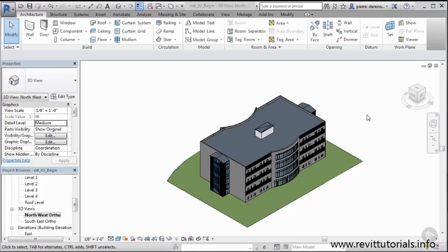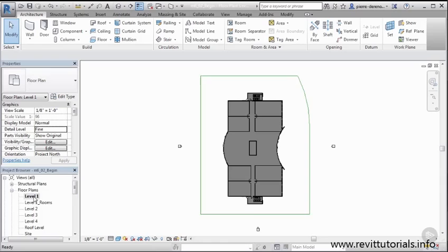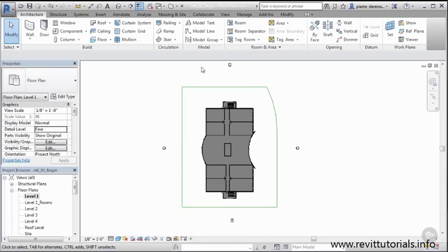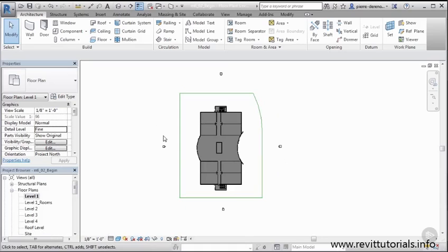So when I'm working with a camera, I can either set that up in a 3D view, plan view, site view. I'm going to do it on level 1. So let's go ahead and jump to floor plan level 1 really quick. Now, I could have done this in a site view, but I like this view here because it's going with more my project north, and I'll be able to place my camera a little easier. Had I gone with the site view, it would be to the actual north. My model would have been set up at an angle.